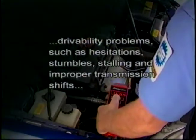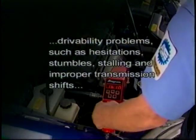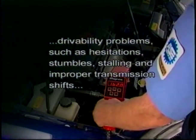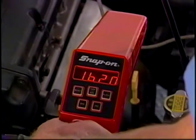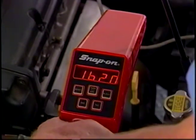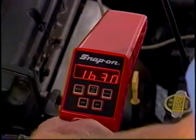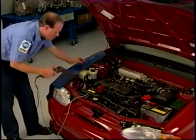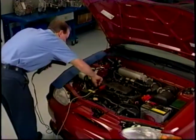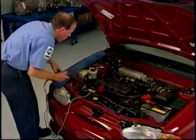Too often, drivability problems such as hesitations, stumbles, stalling, and improper transmission shifts are simply the result of an improperly adjusted idle speed. Many manufacturers have specific sequences to set the idle speed correctly, so make sure to follow the procedure for the vehicle you're working on. When the idle speed is set correctly, move on and check the timing.